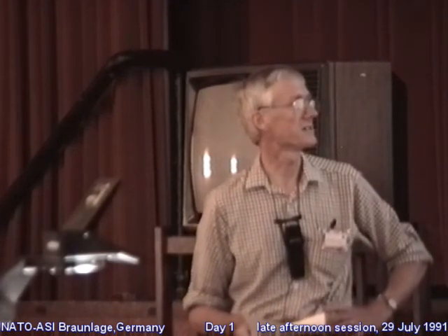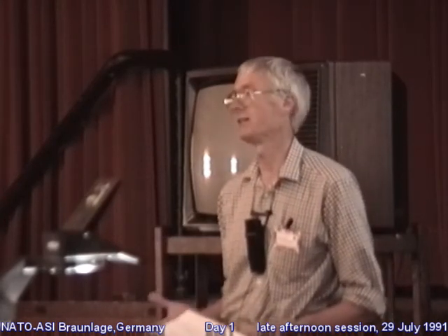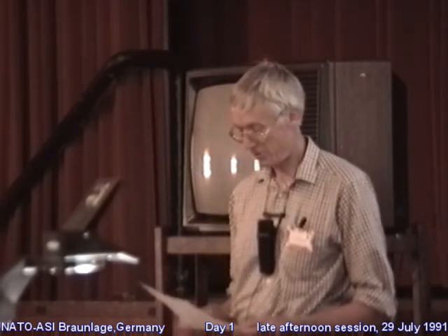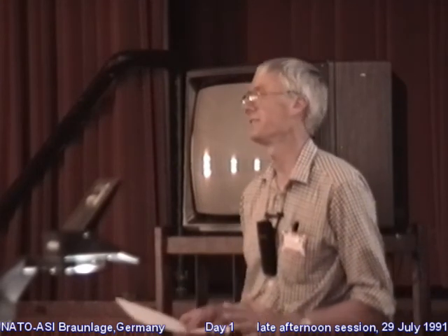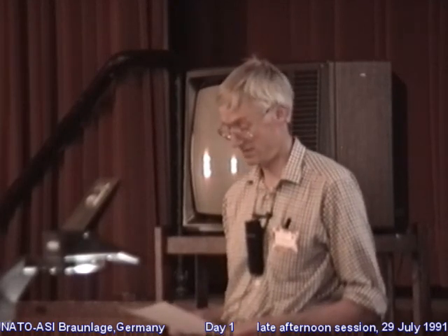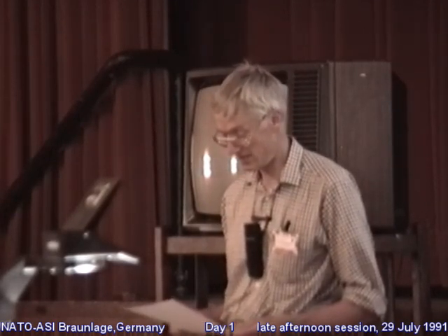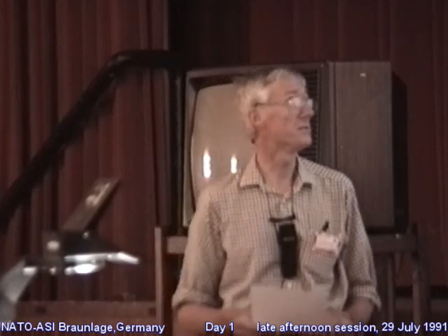And then there is the JKRS fracture mechanics approximation, which involves a balance of energies. You work out the sum of all the relevant energies and you minimize it with respect to whatever variable you want to work with. The approximation there is that it takes account of all the elastic deformation, including that provided as a result of the surface forces, but it neglects any intermolecular attraction that acts outside the contact region.